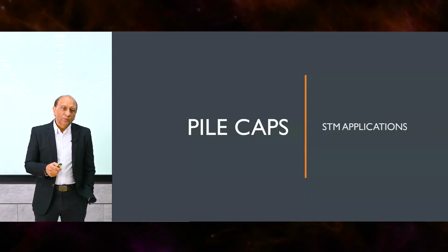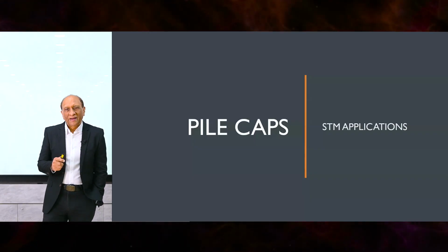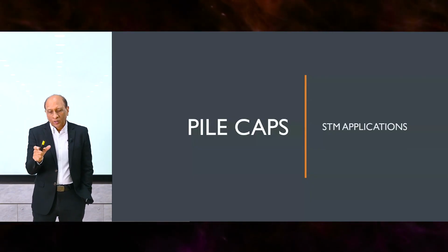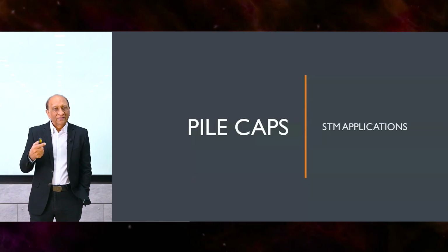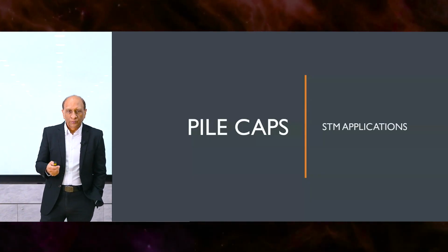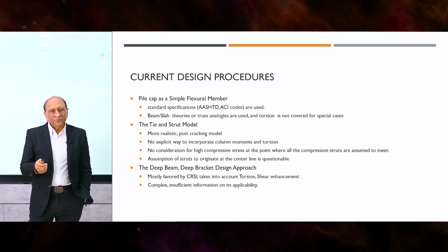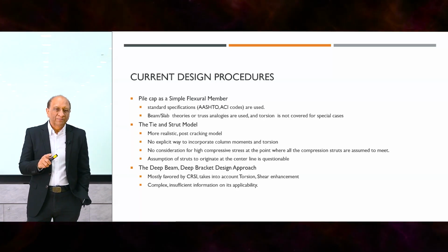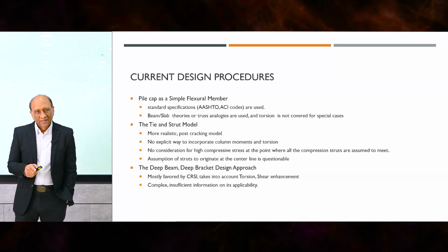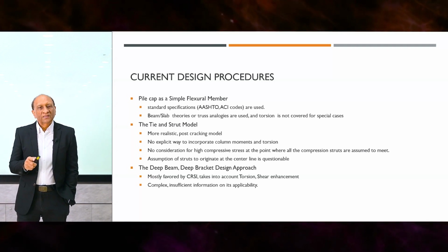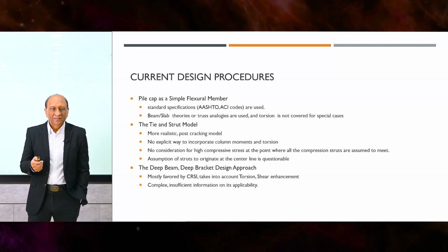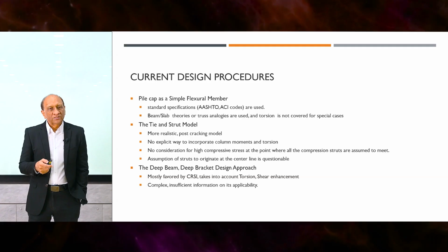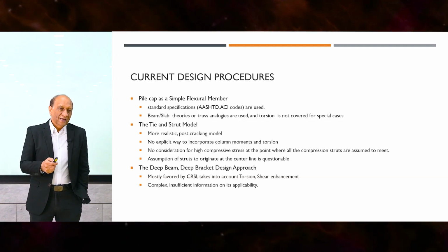as a guideline. Another very common application is the pile caps, because pile caps are very large structures, deep but small, with large loading, large sizes of the supports as well as columns. So pile caps were designed as simpler flexure members, which doesn't work, and it was used a long time. Beam slab, all of these don't give good results. The strut and tie model is most preferred by bridge engineers and many engineers who design pile caps, although the footing approach or the deep beam approach or bracket design approach also has been used.